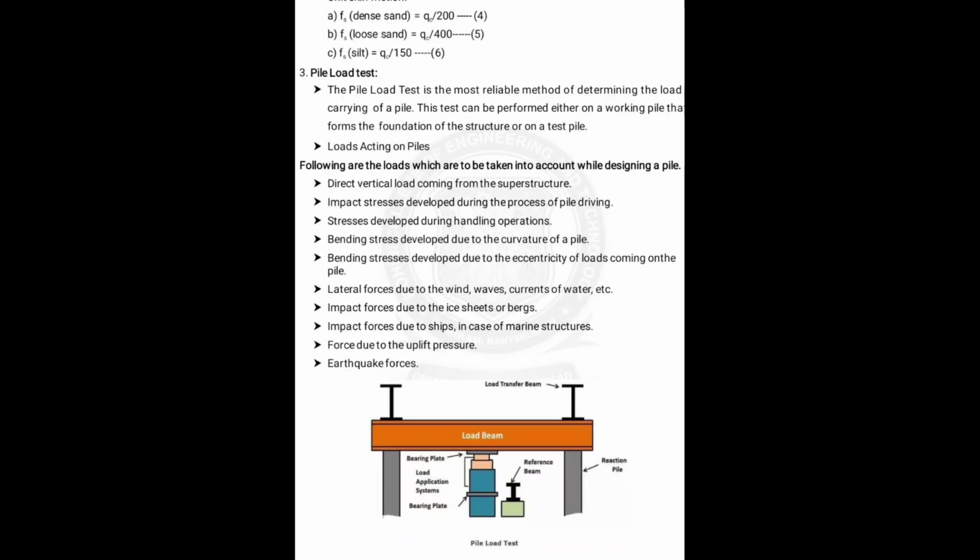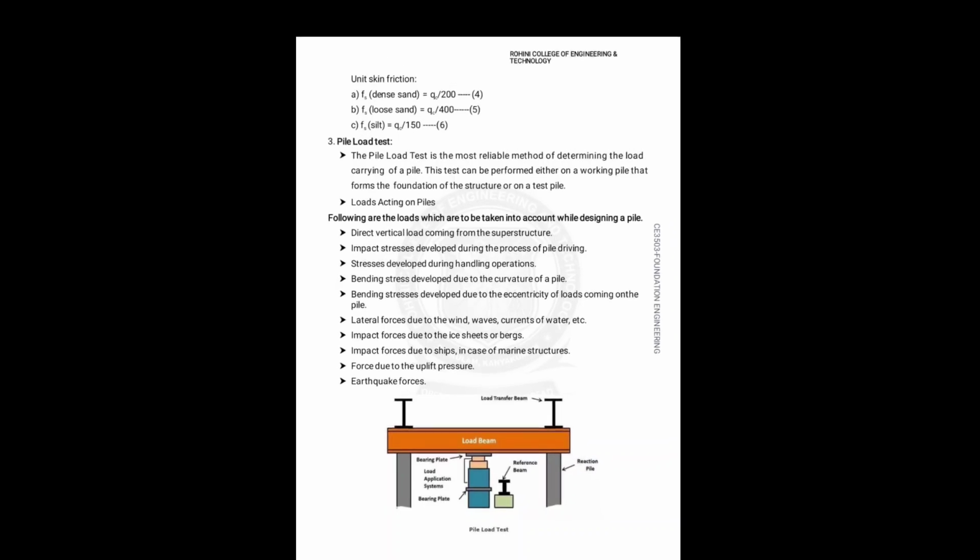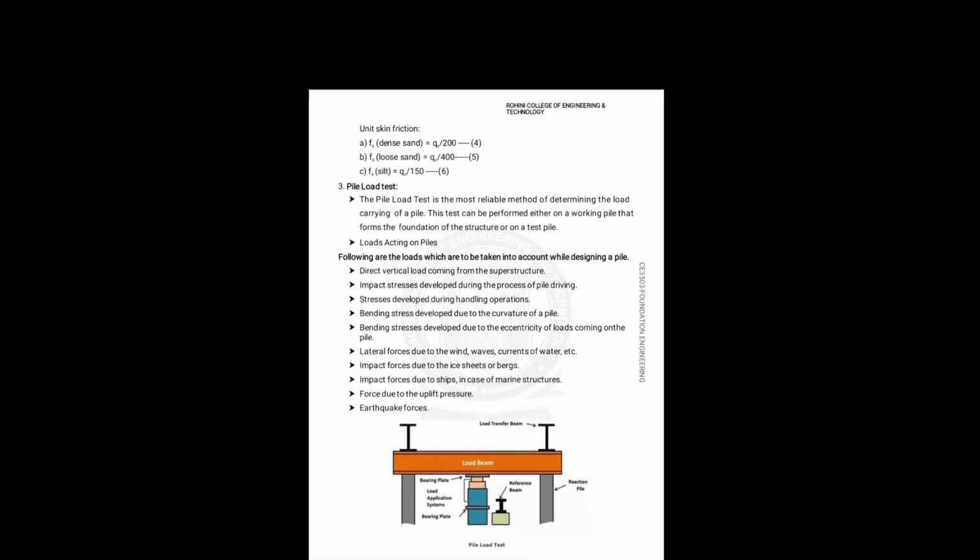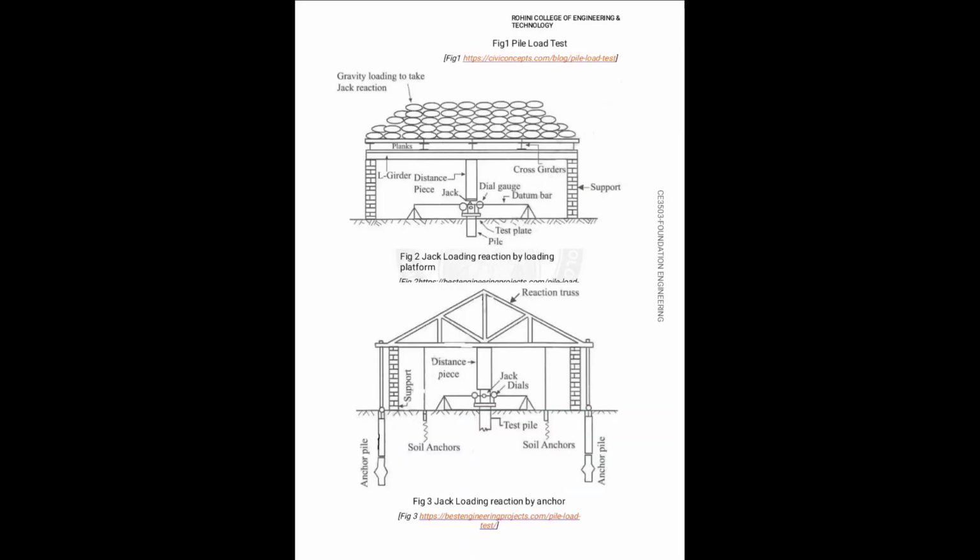Direct vertical load coming from the superstructure, impact stresses developed during the process of pile driving, stresses developed during handling operations, bending stress developed due to the curvature of the pile, lateral forces due to wind, waves and currents of water, impact forces due to ice sheets or bergs, force due to upward pressure, then earthquake forces. These are the loads which are taken into account while designing a pile.